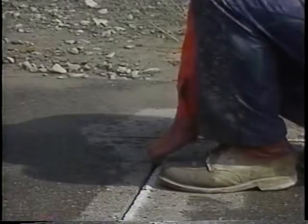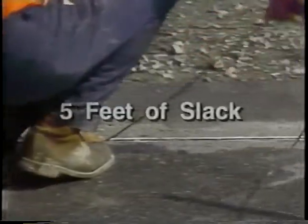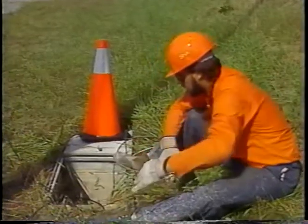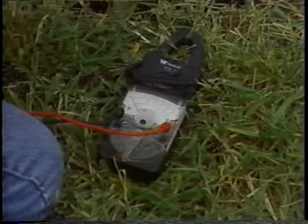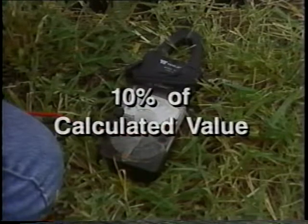Now it is time to install the cables. Seat the cable in the sawed slot, allowing 5 feet of slack in the cable at the pull box. Each cable should be identified by lane or by probe. Then, using a volt-ohm meter, check that the series resistance or continuity of the probe and the cable is within 10% of the calculated value.